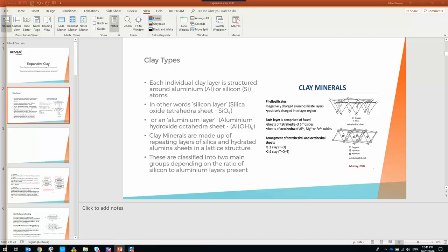Now the next one is fully suspended on void former. This basically looks like a slab on ground, and we use void former, which is just collapsible cardboard, to form the void underneath. So it's still a fully suspended system, but the main disadvantage is if you've got a lot of drainage under your slab, I prefer to have the drainage fully encased in the structural slab, otherwise you can just cause yourself grief. So it's difficult to do that.